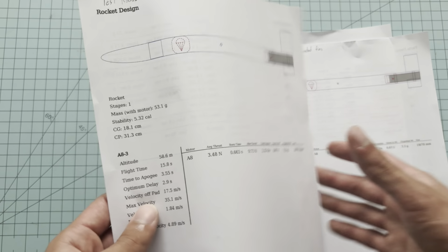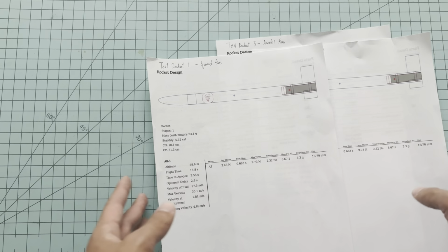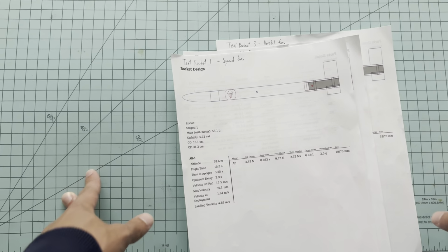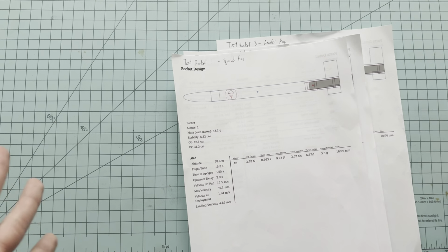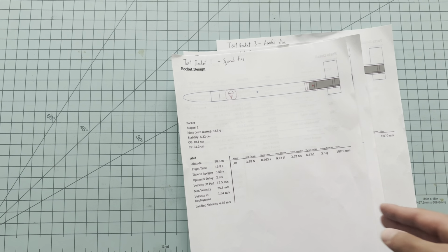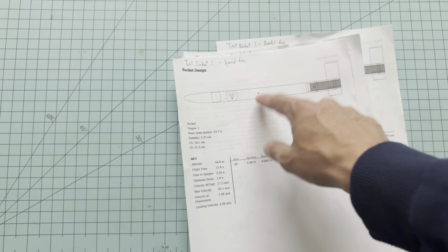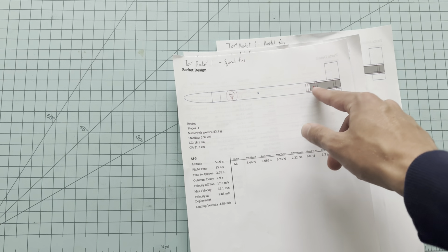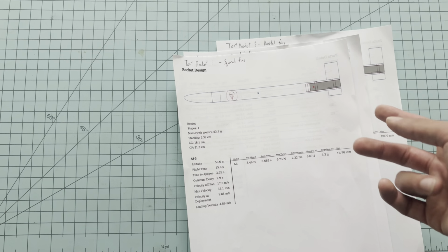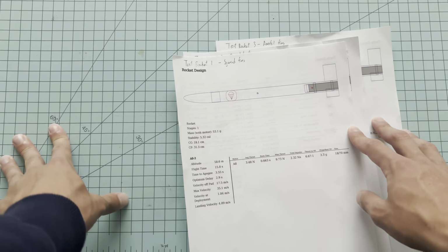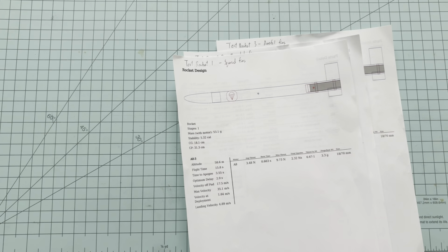We're going to be using the A83 motors. Now, the general rule of thumb, not always the case if you're new to designing model rockets, is that you want the center of gravity to be 2 calibers ahead of the center of pressure. Test it with the motor in, with all the motors that you might be planning on using. This is overstable because it's 5 calibers, but again, it should be fine.